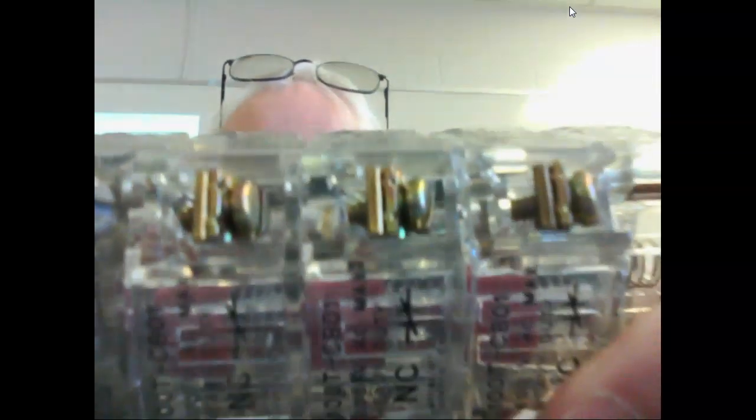On the left-hand side, we've got all normally closed contacts. And over here, somehow we got a normally closed in the middle of a normally open, but they just stack on here. And when you move the operator, it comes up here and just daisy chains down through all your contact blocks.